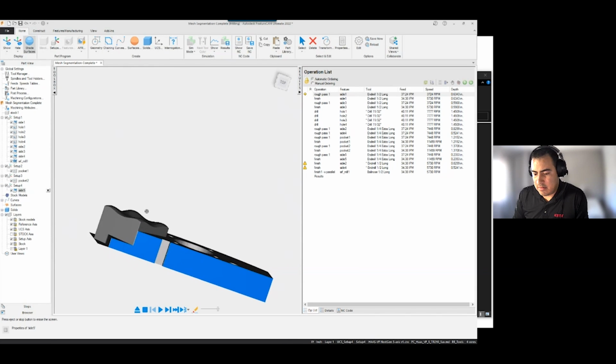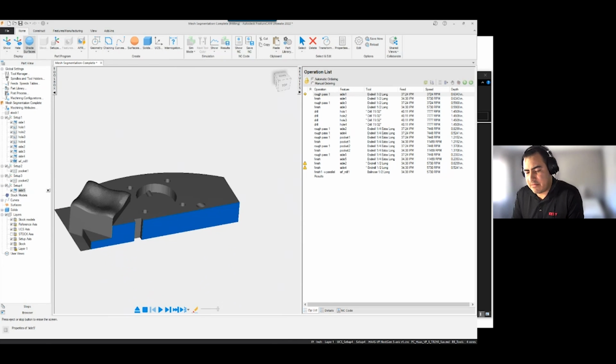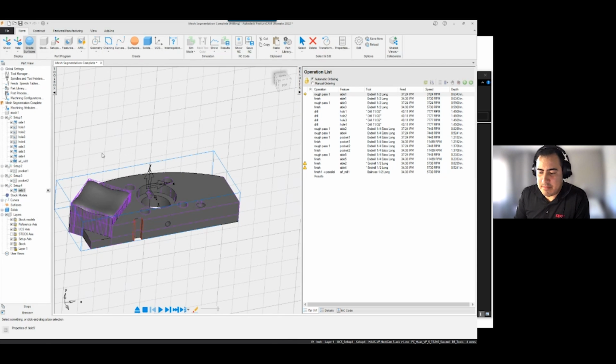And then it actually does do the surfacing, right? So even for the surfacing, I didn't really talk about this, but you do have machining configurations that can apply to some of these surfacing strategies. So if you are doing a lot of surfacing and you find yourself often changing parameters or settings, that's something that FeatureCAM can do really well: you can specify your step overs. If you have specific configurations for that, you can automate that inside of the software.